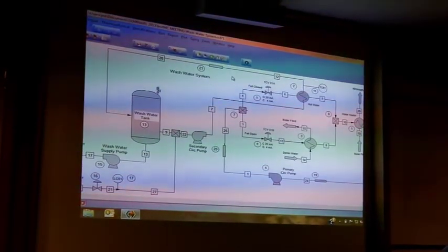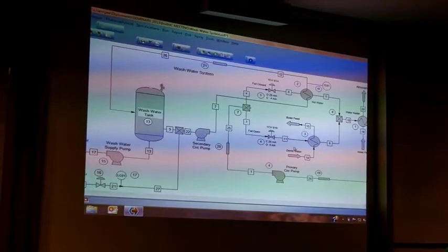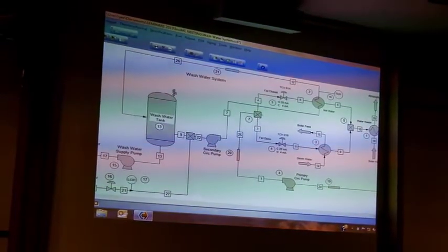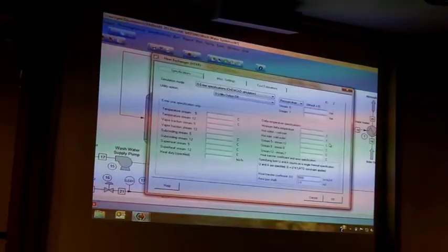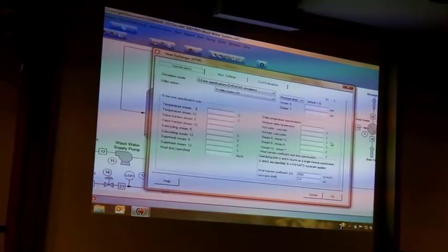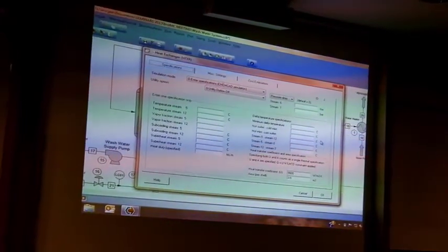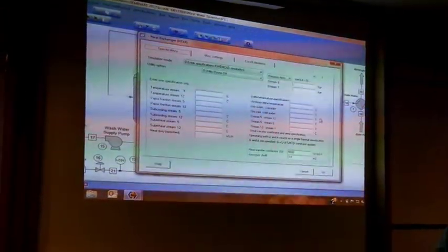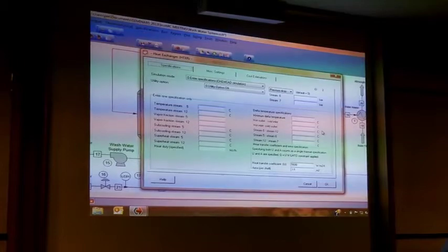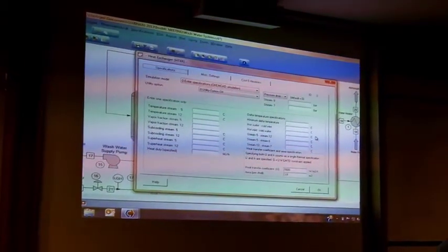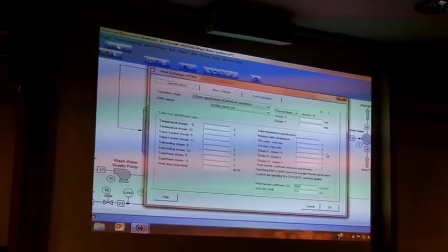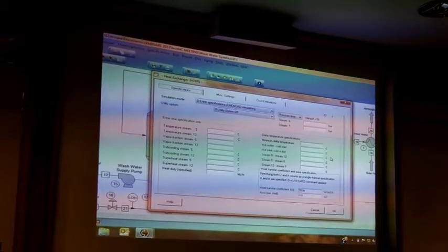And just thinking about that then, John, at first sight, the heat exchanger there looked like a fixed variable. When you had that heat exchanger up there and the heat transfer coefficient, it looks like a fixed value there. It is. But what you're saying is you can actually arrange for it to be variable. Yeah. But if I put a real heat exchanger in there, it'll vary itself as well. You might be asking me how confident I am about that heat transfer coefficient. I know I've got constant flow on the shell side. I know I've got constant flow on the tube side. I'm not manipulating the flows, so I can be confident of that coefficient.